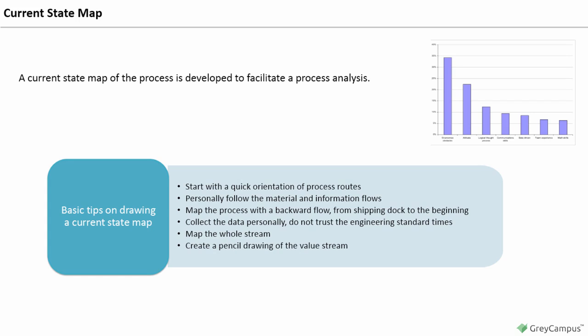Some of the typical process data included are cycle time, CT, changeover time, COT, uptime, UT, number of operators, pack size, working time, that is minus breaks in seconds, WIP, and scrap rate. An analysis of the current status can provide the amount of lead and value-added time. In many situations, teams take on the task of data collection. Both individuals and teams find it beneficial to develop a VSM data box in advance. Value stream mapping definitions worth noting include value-added time, VAT, the amount of time spent transforming the product, which the customer is willing to pay for.